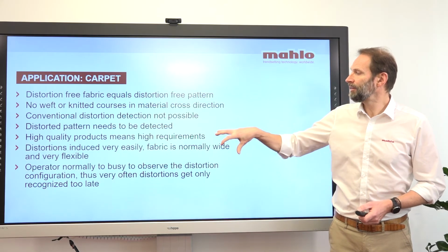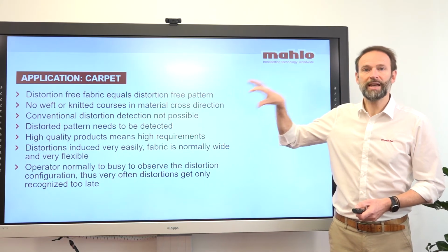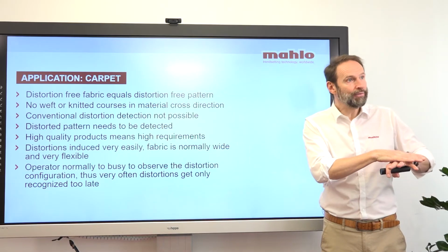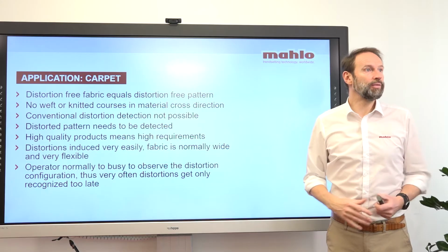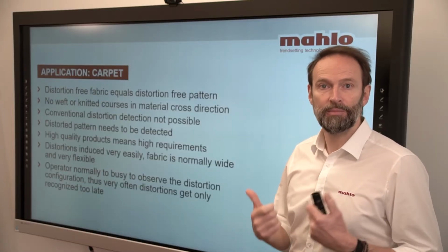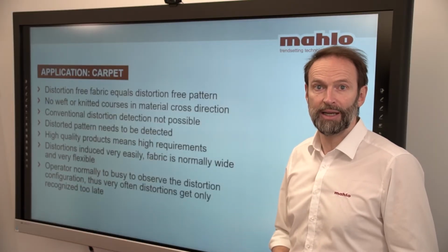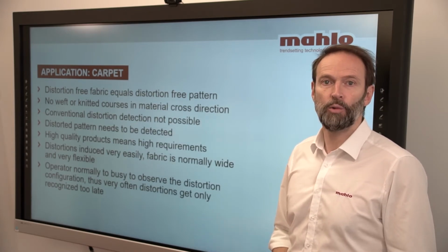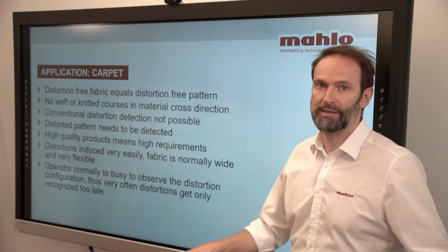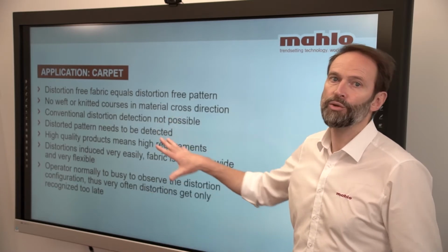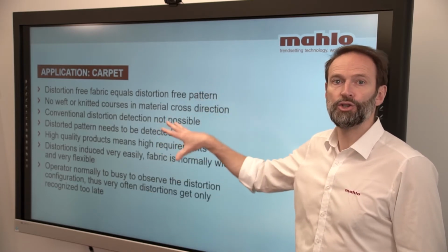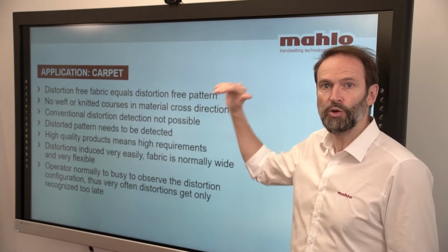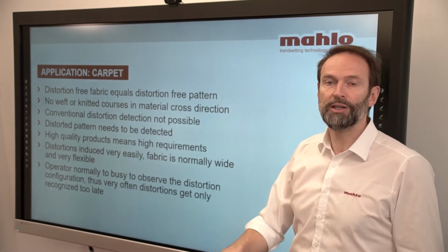It is very, very important that we do that correction at that step, because afterwards, when we have the back of the carpet applied to the fabric, there's no way that we can really correct it anymore. Then this whole thing is fixed forever. So we have to correct the bow and the skew distortion at that point. We have to make sure that the repeat is always the same at that point.